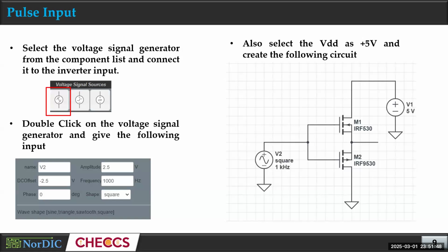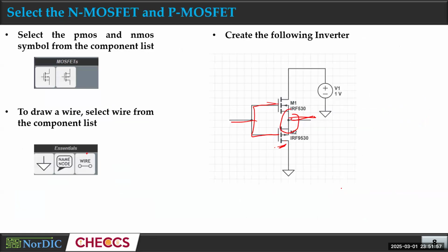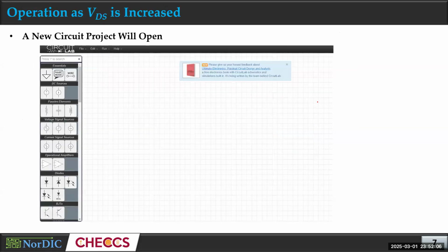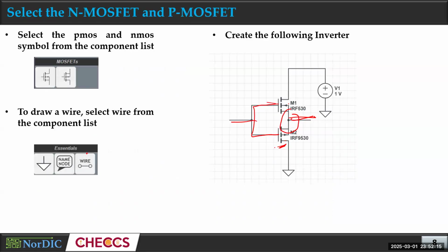We'll bring in the voltage source, which will be this VDD here, and we'll also bring in ground here, which will be connected to the source. Bring in the VDD voltage source from there. This is the DC source actually, so you will bring a DC source and connect that with the source of the PMOS here. So this will be our DC source. Okay.